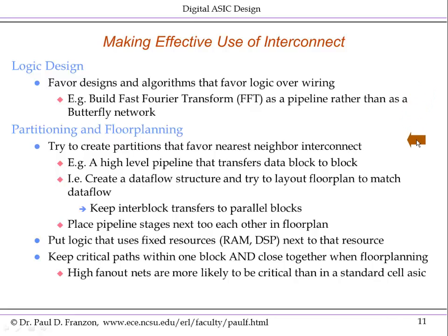What this means in general is you want a physical architecture that goes from neighbor to neighbor, so you don't have a lot of long-distance wires that have to go across multiple elements. You should be able to draw your design as largely a pipeline design with neighbor-to-neighbor interconnectivity. This will map a lot more efficiently into an FPGA than a design with lots of random wiring that spans multiple logic blocks.